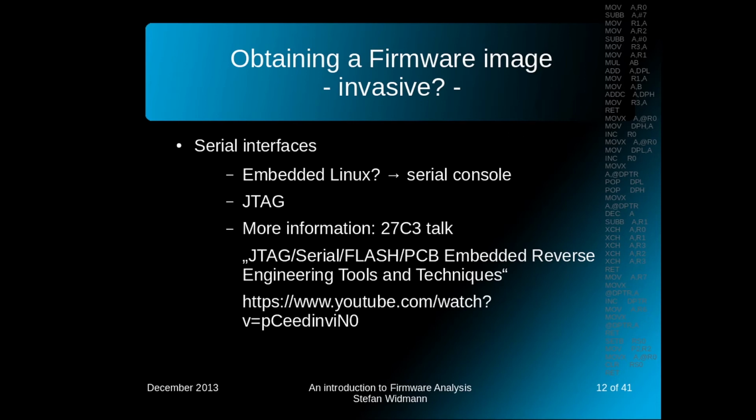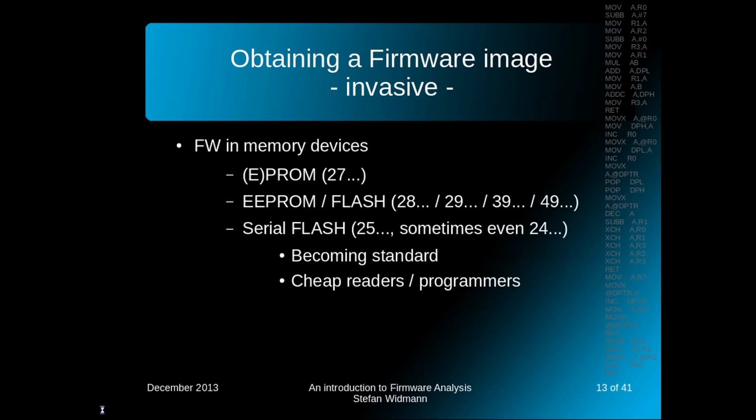So, still no firmware? Get your screwdriver, let's void warranties. We open the device and we search for memory devices on the PCB. If you have a very old device, maybe you will encounter EPROMs or even PROMs 27 something. If it's a little bit newer, you might see EEPROMs and flash 28, 29, 39, 49 something, and the big flash devices and bigger devices with 48 pins, for example, with various other names.